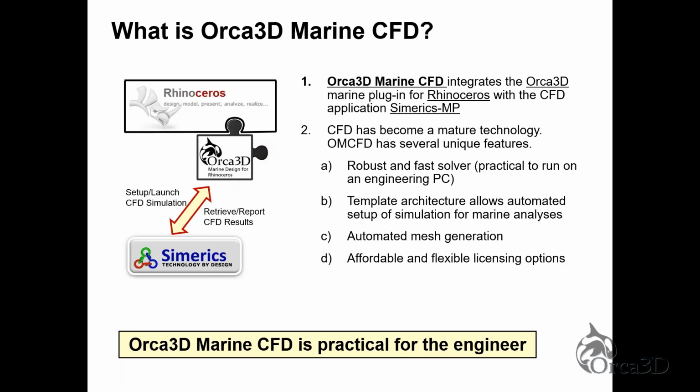In order to make it approachable or useful for a particular problem, you have to set a lot of settings for that general purpose tool. The template architecture allows that setup of the simulation to be automated. So there are templates for different industries. And of course, there's one for the marine industry. We call it the marine template. So the marine template handles a lot of the setup, things like the automated mesh generation, picking the length of the simulation, how many time steps to break the simulation up into, and many other things as well. That's really the technology that encompasses all the knowledge and expertise of the marine CFD expert so that you don't have to become an expert.